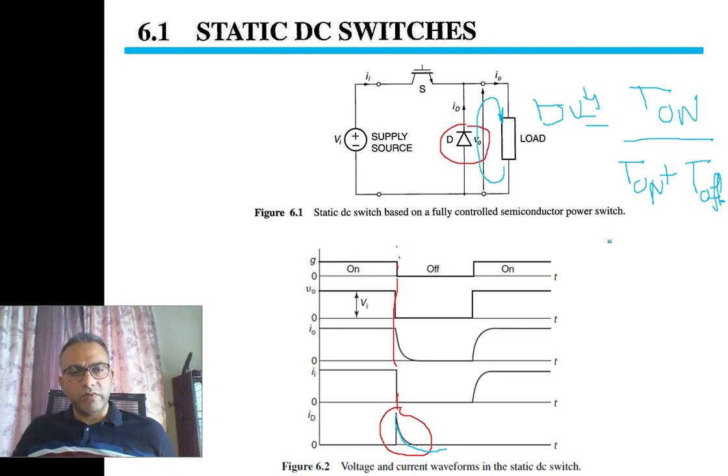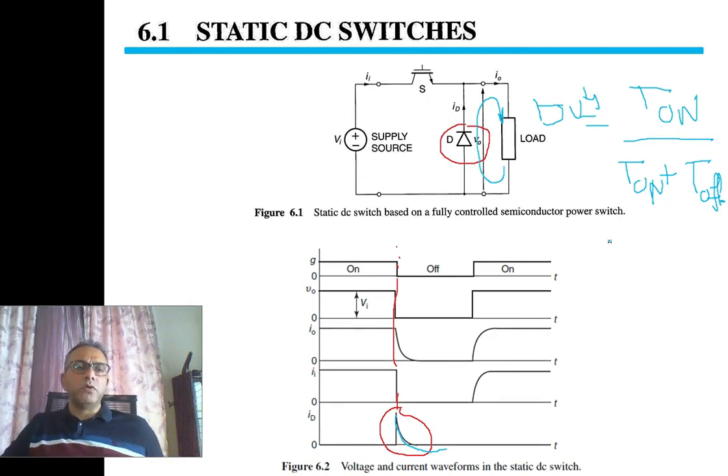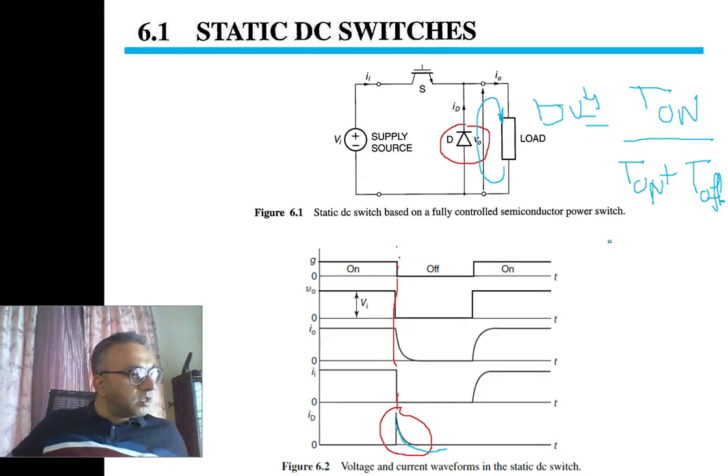As my students have already studied this in undergraduate courses, output voltage is variable from 0 volt to V in in the case of a step-down DC-DC converter, and the function is V out is equal to V in multiplied by bracket T on divided by T on plus T off bracket closed.